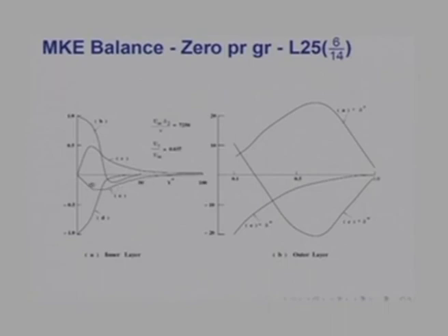That means the energy is being given away to produce turbulence in this region of about y plus of 20 onwards. I mean, its maximum is at about y plus of 20. If you go now to the outer layers, here each of the terms has been multiplied by delta plus, and delta plus, as you know, depending on where you are in the turbulent boundary layer, would be of the order of 800 to 1000 or 1200.